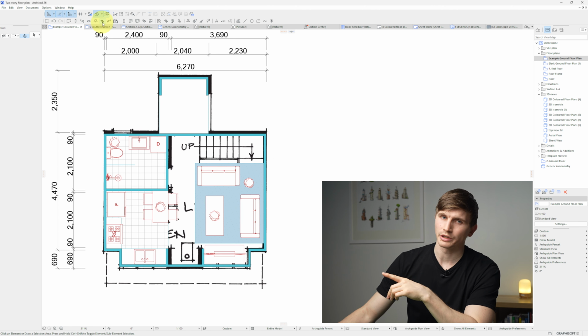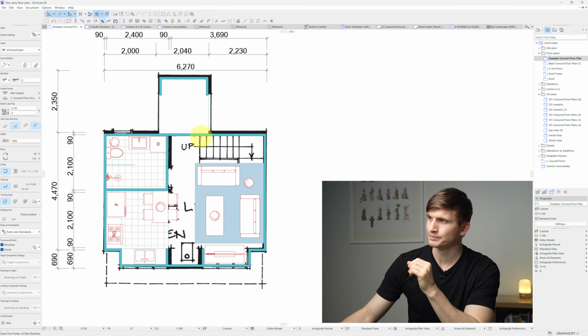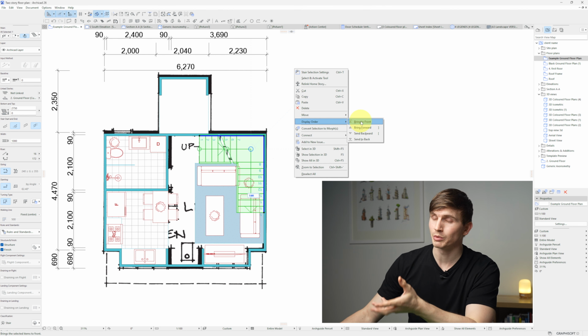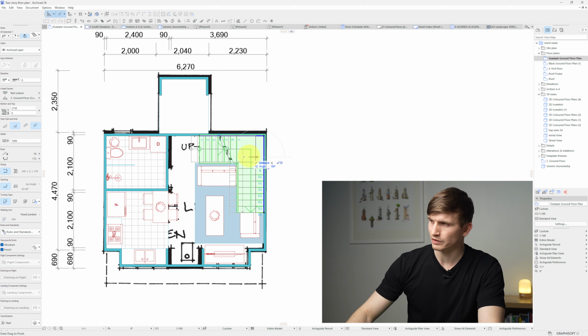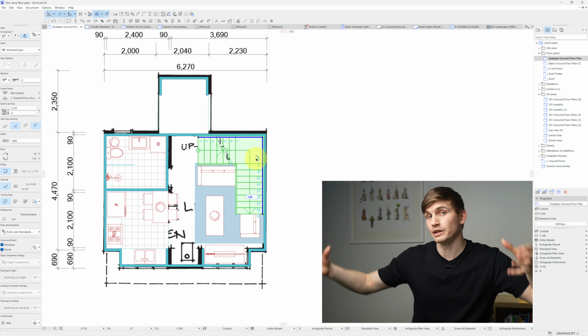So from here we can just click on the stairs, go to our favorite, and I think an open riser timber one will work well. So matching the sketch, I'll click once, I'll click twice, and I'll finish it up with a third click. I'll hit escape, and I'll bring this one's display order all the way up to the front. Let's inset at 50, and another 50 for the stringers so they're on the inside of the stud wall.